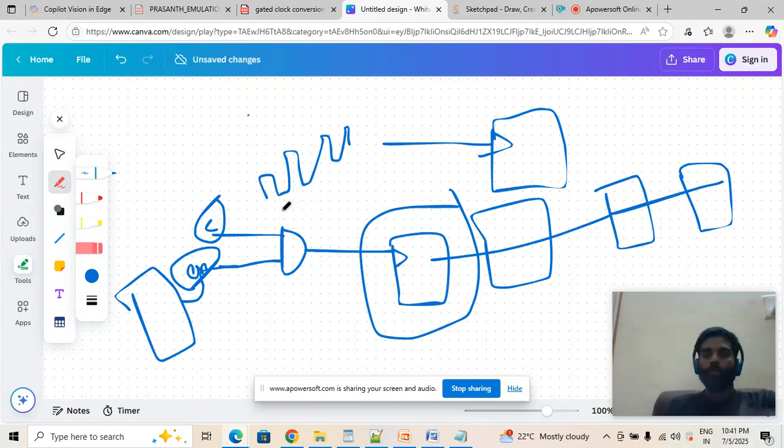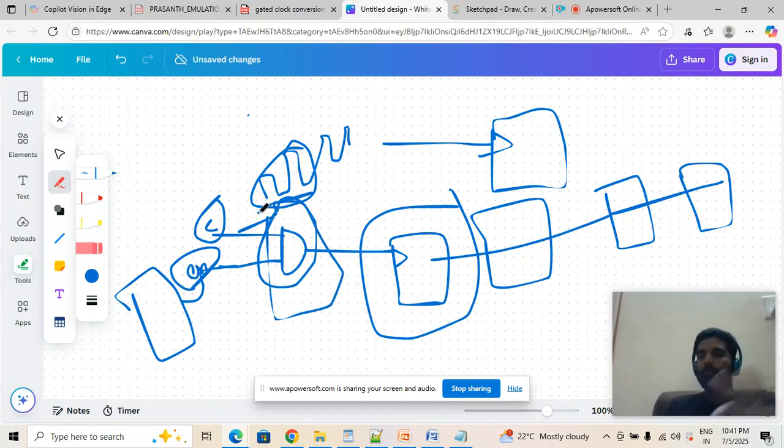Okay, so there is a disadvantage. If you use this gate level clock gating, it will suddenly create some glitches. Suppose you're activating this enable in the middle of the clock, so you don't get to see the full clock. The clock period will be cut down. It's called glitches, right? It's a combinational circuit, right? So for that reason you can go for some register based clock gating, whichever is possible. So that will give you the complete flexibility in implementing the clock gating.